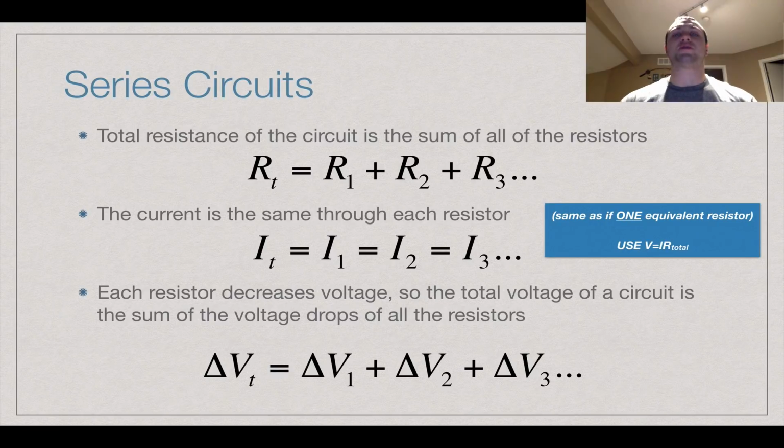So what that total resistance means is if you were to condense everything down into a single resistor, that's what that value would be. So it's taking a variety of resistors that are out there, and if they're in series, add them up, and it would be the same thing as putting that one equivalent resistor in that circuit. So again, to find that total resistance when in series, we just add up those resistors.